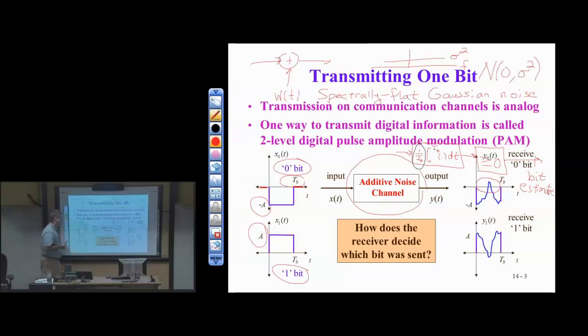Okay, so this is an averaging operation. I'm going to get 1 value that comes out of this averaging operation per symbol time, and really what it is, it's an estimate of the symbol amplitude for the nth symbol.